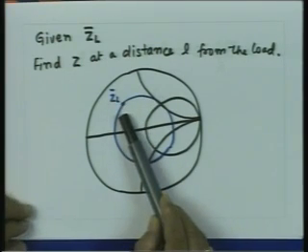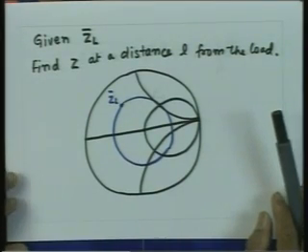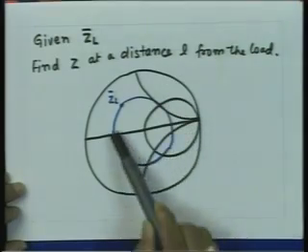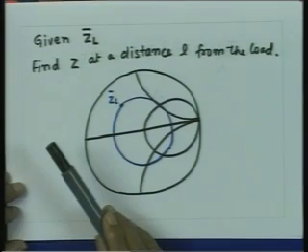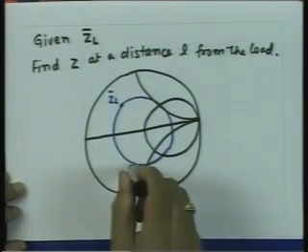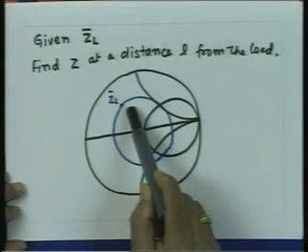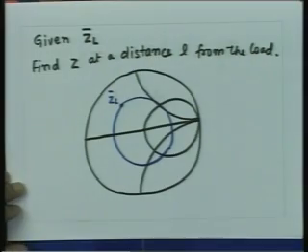And that makes sense, because if you recall the characteristic of transmission line, we had seen that the impedance characteristic of transmission line repeats itself for every distance of lambda by 2. That is what essentially we are reaffirming: by taking one rotation on the constant VSWR circle, we reach the same point, and beyond that again the characteristics are repeated.